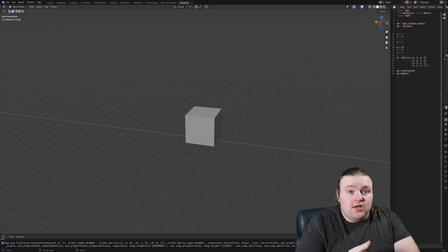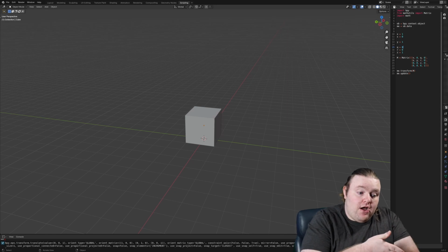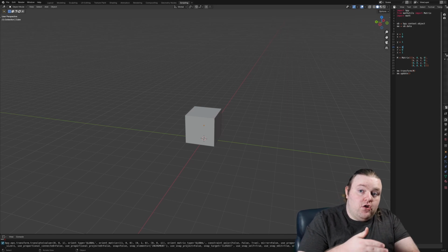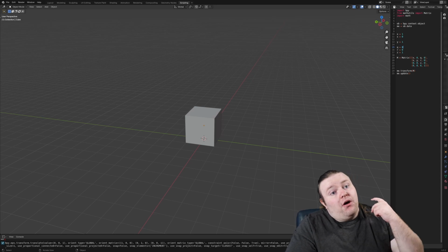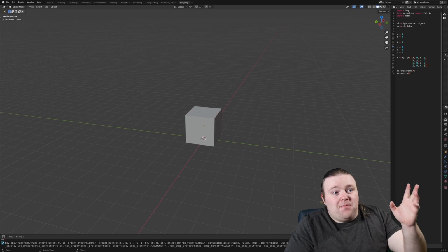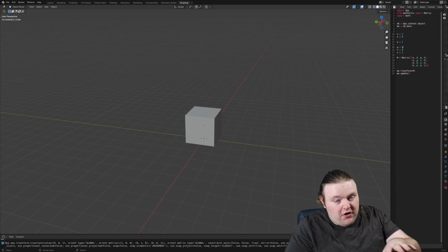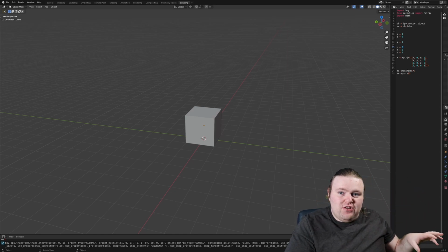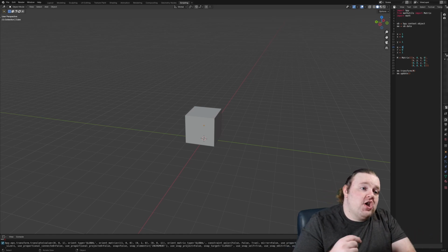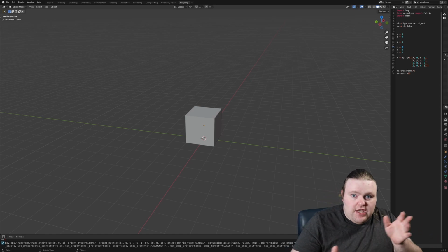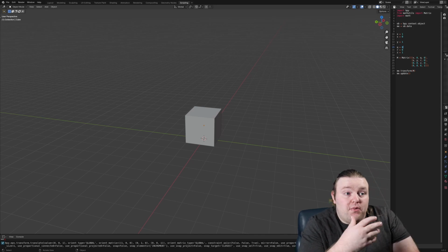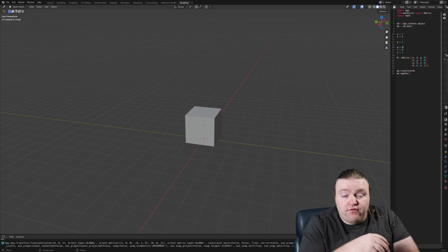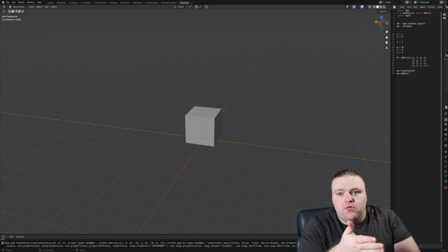I can't correct them because I can't correct them separately and they are different. One number does not make it correct in both directions. So that is also wholly useless. But we can actually do scale correction for a specific material on our printer in the same transformation that we do with skew, and we can treat each axis separately the same way. So if you have a scaling problem, a dimension problem, not necessarily skew, but literally that one side is just behaving differently, then this also is a solution.